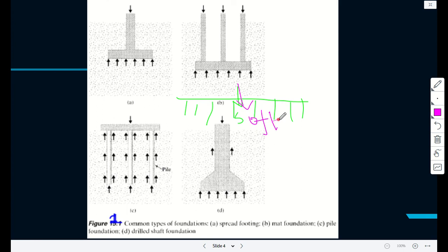If you apply soft clay, it will sink and cause a problem. So what we need to do sometimes, of course, if it is possible, is spread the load to a wider area, because probably if you put the foundation here, there might be excessive settlements around, such that your structure collapses.